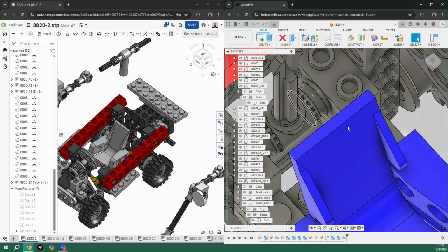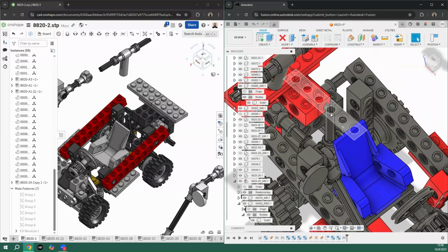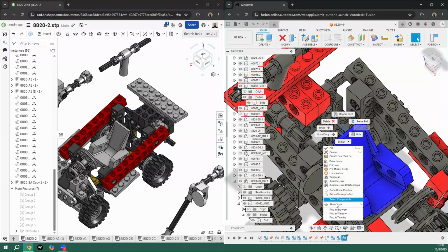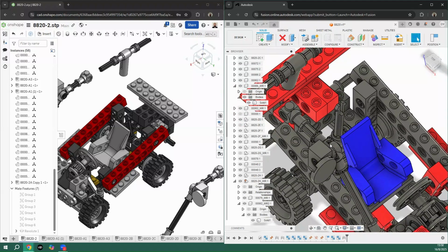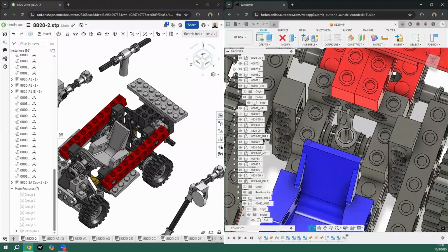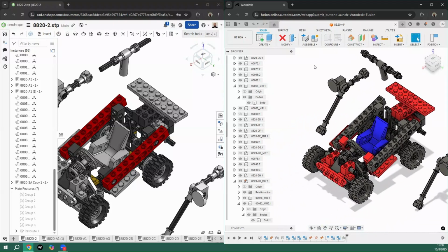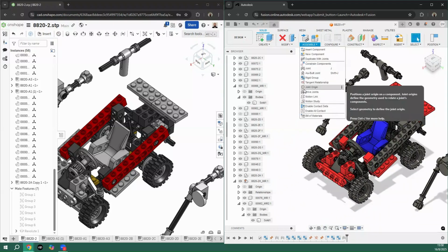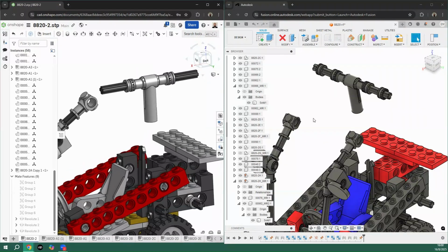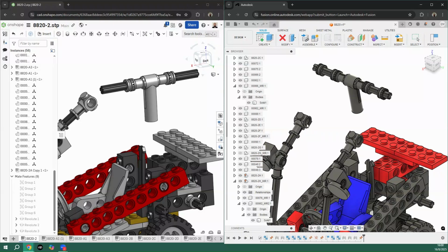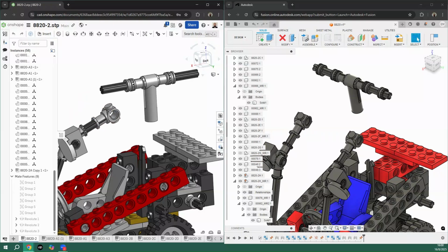Okay, let's click OK. Now it is made in position, and I can drag it and I have the same movement. Perfect. This guy in here, I will right click and click on show hide, so it is not going to be there. That's another way to hide the mates. Okay, perfect. So now let's do exactly the same thing with the other two arms. Okay, so we got our arms pivoting as expected.